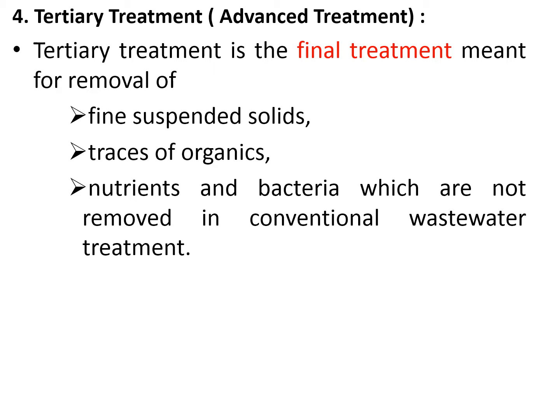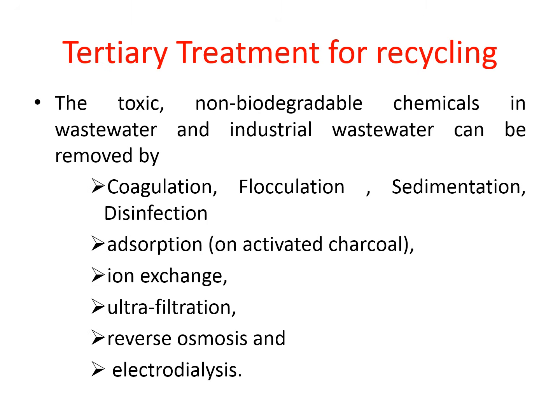The last treatment is tertiary treatment. Basically, it's an advanced treatment. If you want to reuse or recycle your wastewater, then it has to be further treated to remove fine suspended solids, traces of other remaining organics, and nutrients and bacteria which are not removed in the conventional wastewater treatment plant. For recycling, different methods are used, like coagulation, flocculation, sedimentation, disinfection.